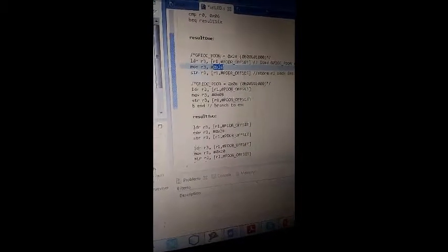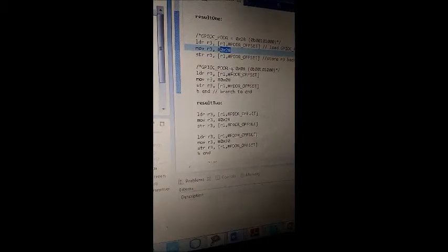Actually, this is our output. Then our output is 101. So all the output is equal to 0010 1000. So we change to hexadecimal, which is 0x28. Then back to our coding. After moving 0x28 to R3, we will store R3 back into GPIOC PDDR. Then turn to GPIOC PDOR.